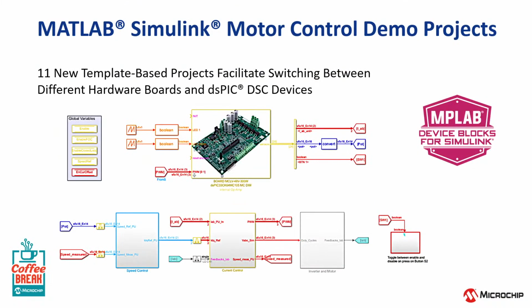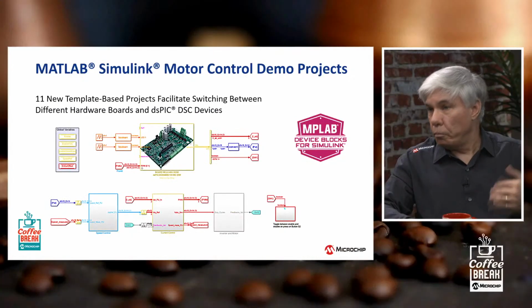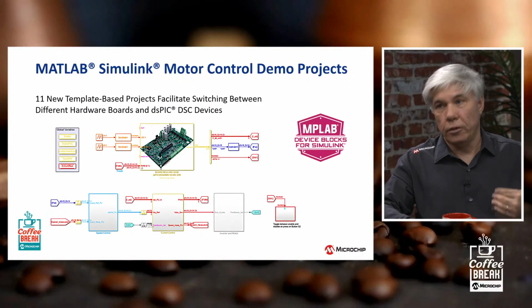Okay. And these projects are template-based now so that you can easily switch between a different dsPIC device or a different hardware development board or a different version of the field-oriented control algorithm, model, simulate, and then generate the code and download it to the board and run the motor.